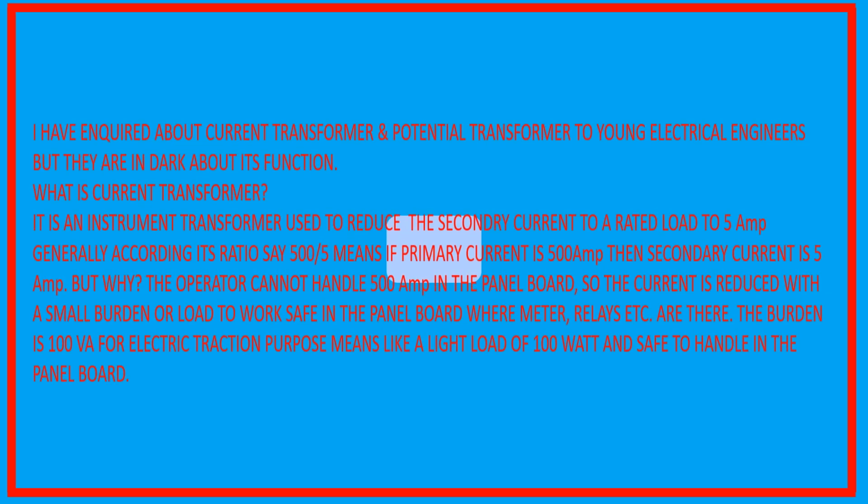I have inquired about current transformers and potential transformers to young electrical engineers, but they are in the dark about their function. What is a current transformer? It is an instrument transformer used to reduce the secondary current to a rated load of 5 ampere, generally according to its ratio, say 500 by 5, meaning if the primary current is 500 ampere, then the secondary current is 5 ampere.